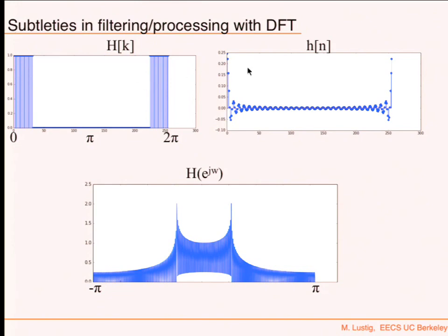But now that's a problem. If I had a linear phase multiplying this, that would shift the impulse response such that it's centered around the middle. And as it turns out, if I had done that, then I would have actually got a decent low-pass filter with the DFT too. Because then that part would not alias. I would circularly move it to the center, and then everything would taper off. So the DTFT would have looked much nicer.